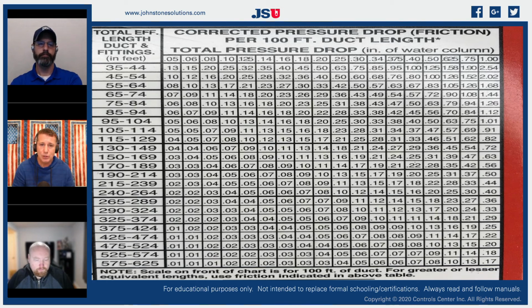So what I can do, if I want to get an accurate representation of how much restriction is in that system, I can use this corrected pressure drop calculation chart on the back. And what it's going to do is it's just going to tell me how much to correct that pressure drop so that I can change the size of my ductwork accordingly.